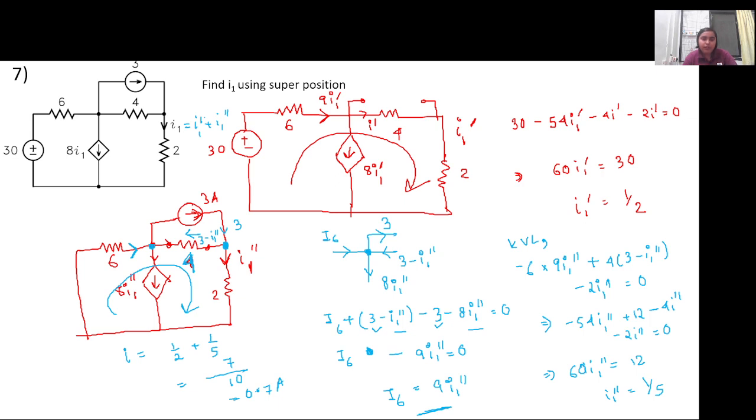Yes, ma'am. Okay. So circuits with dependent sources are pretty straightforward right now. As the circuit grows bigger, these network theorems will help in figuring out the branch voltages, as we had seen previously when there were only independent sources. For dependent sources, the dependent source is retained, whereas the independent ones are replaced by their internal resistance when using any theorems, as per the rules. So this is how you will have to solve it.